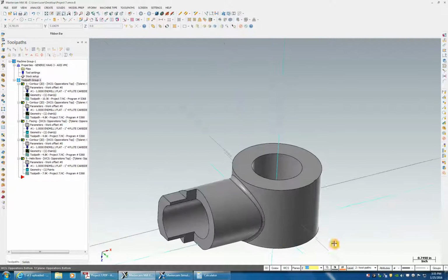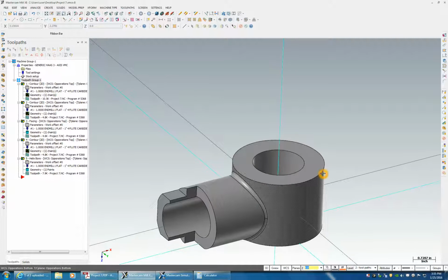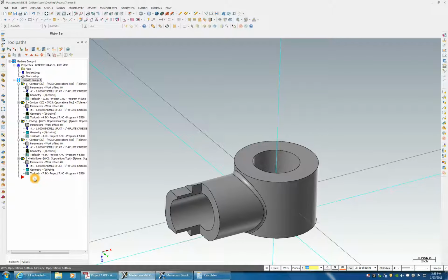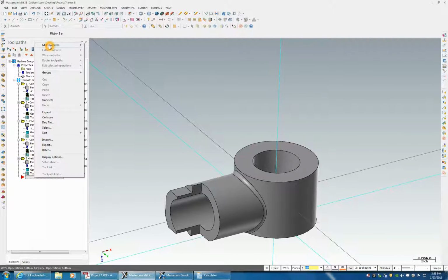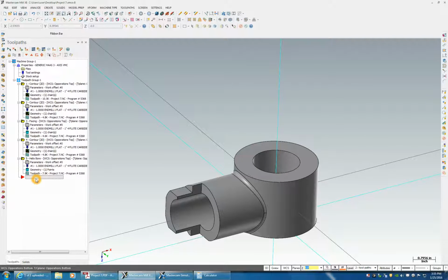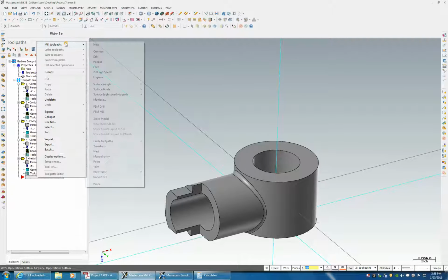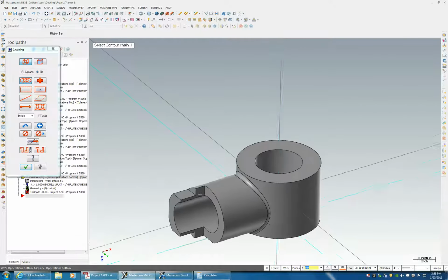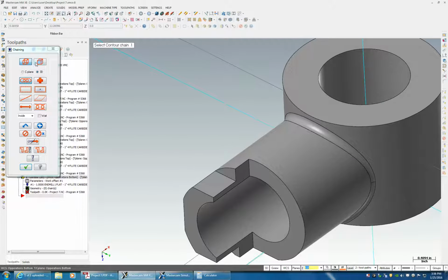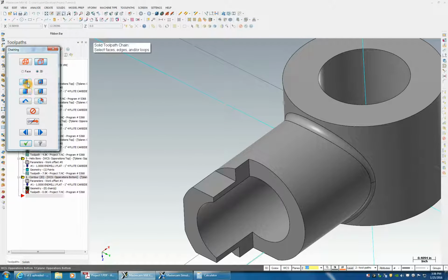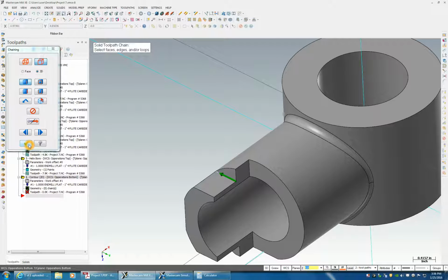Okay, so what do we got to do on this side? It's 2 simple problems. We have this surface takeoff and this tab takeoff. Let's go ahead and start with that tab. Do contour. Now we're probably still going to have some of those weird problems here. Hopefully you are not having that problem. I'm going to use a solid edge. It's going the wrong way. Wait, no, that was the right way, because we want to make sure it's climb cutting.